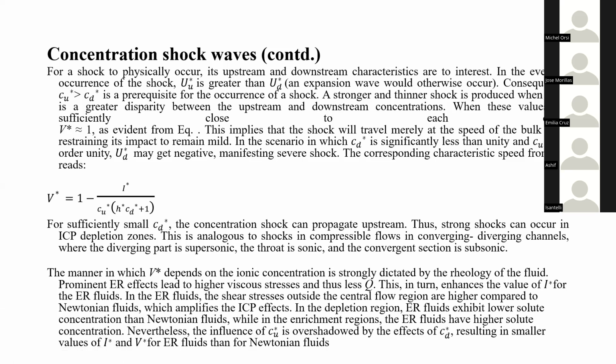The strong shocks can occur in ICP depletion zones. This is analogous to shocks in compressible flows in converging-diverging channels, where the diverging part is supersonic, the throat is sonic, and the converging section is subsonic.